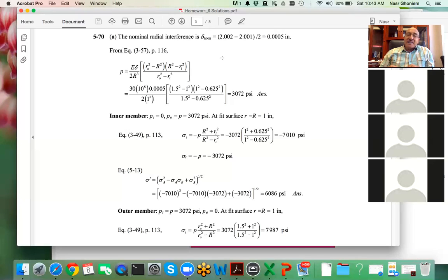So the idea is to use singularity functions, because it gives you one equation for M over I. But that equation has 1 drop at the junction on both sides, 2 drops actually, and a change in the slope in the middle. So he prepared the solution, and he's going to also discuss that.